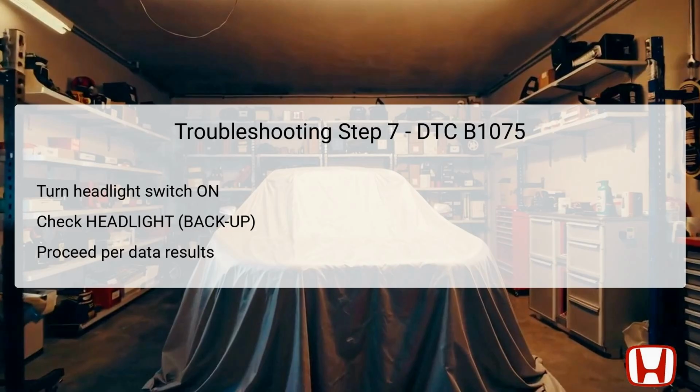This check is pivotal as it determines whether the system recognizes the headlight's operational status. If the information indicator reads on, this indicates that the relay control module is communicating effectively, and one should now proceed to replace the relay control module. However, if the indicator is off, the focus should shift to the next step for further analysis, indicating that the relay control module may not be providing the necessary connectivity to engage the headlights properly.